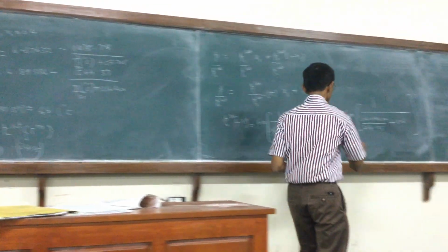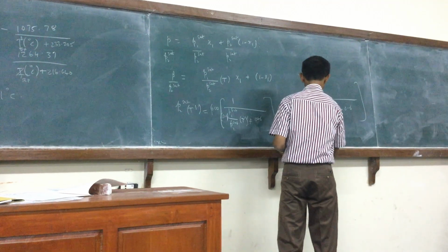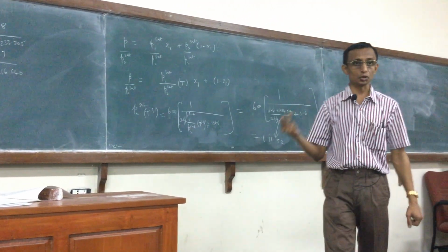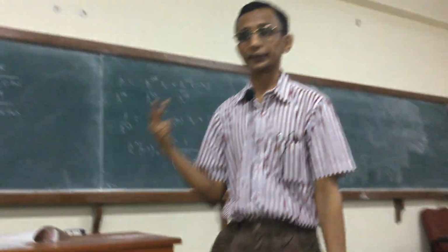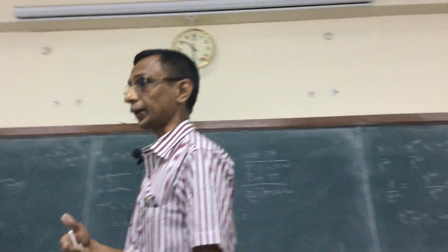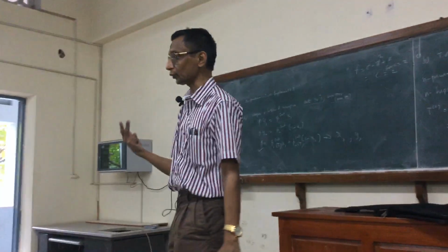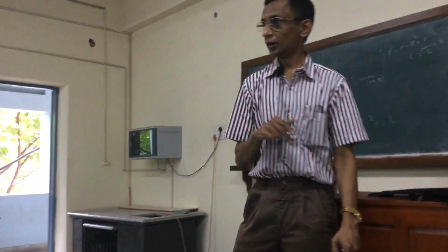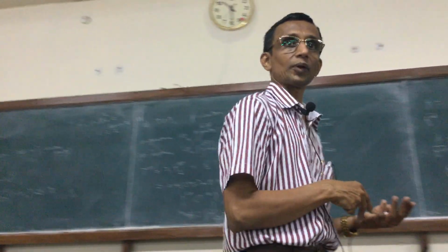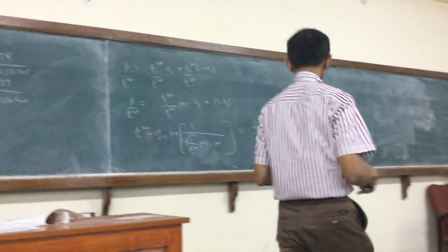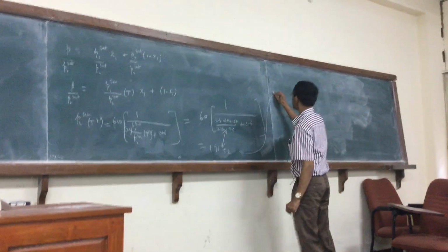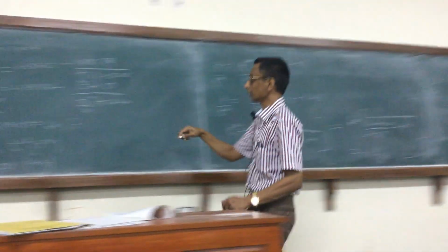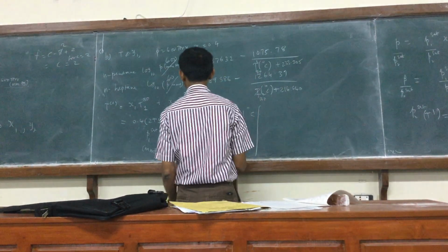171.52. So you can clearly see what we need to compare is 264 versus what I chose for P2 sat at T0. But what I am getting, the new value of P2 sat, is 171, whatever, right? So that means that T1 may be different from T0, clearly. Now I need to use this to calculate T1. So for that I need to invert this. I need to invert only this.